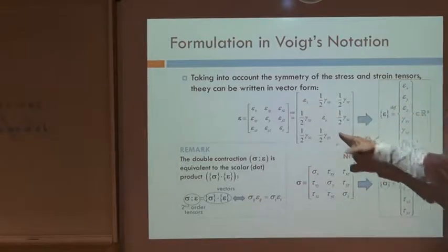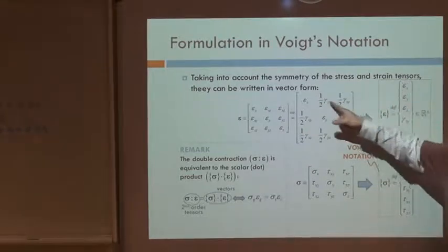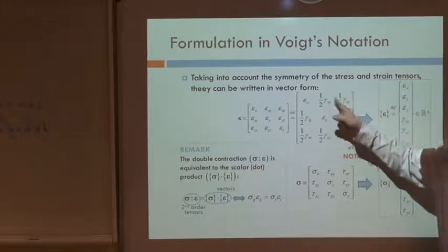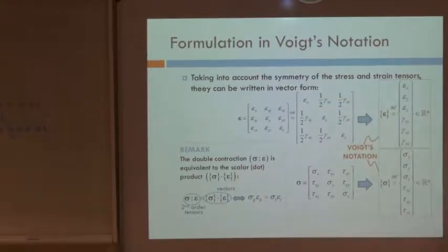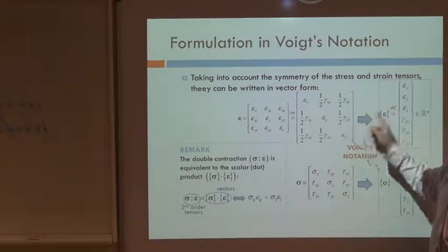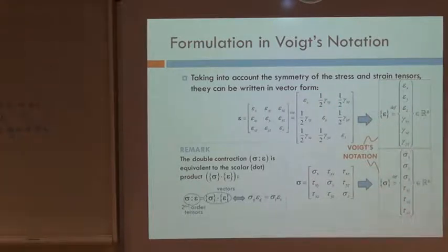First, the 3 elongations, the 3 diagonal terms, and then, in terms of the strains, the 3 shear angles. Note that we do not introduce the 1/2 here, and there is a reason for that. Okay? Of course, if I know that, then I would be able to reproduce the tensor, placing that here, that here, that here, divided by 2, etc. So that's not the problem.